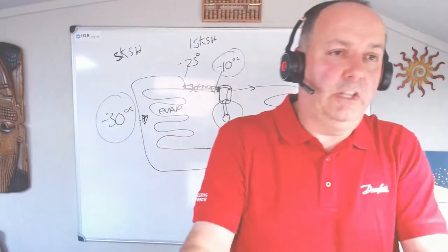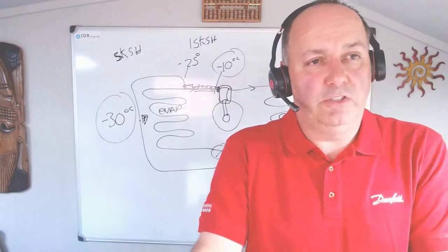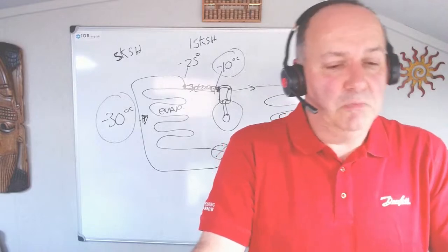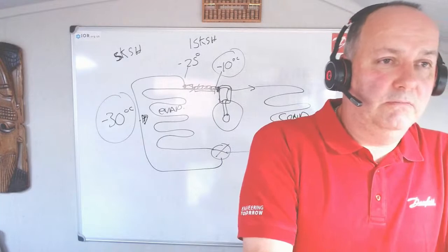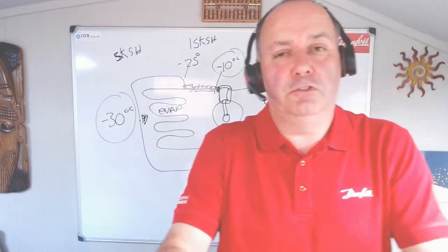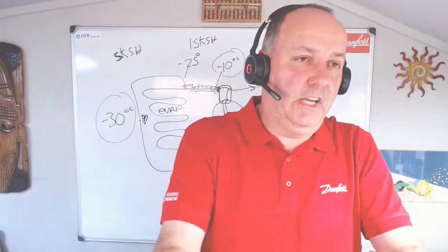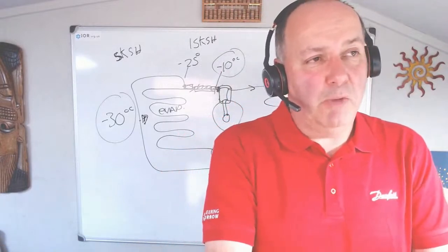So if you stagger it like that, if you've got 10 evaporators installed, I would basically run 9 evaporators and defrost 1, and basically do that through the day. If you can't fit that into a time schedule, then maybe do 2, but it is very much application dependent.